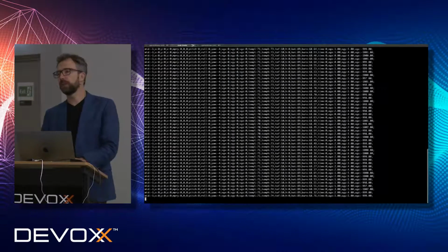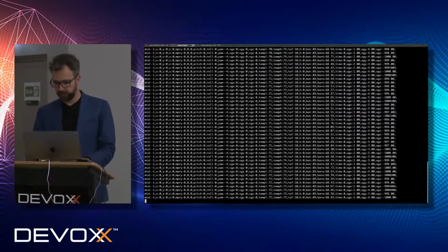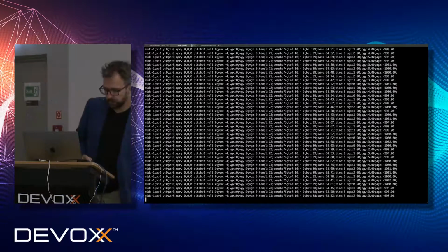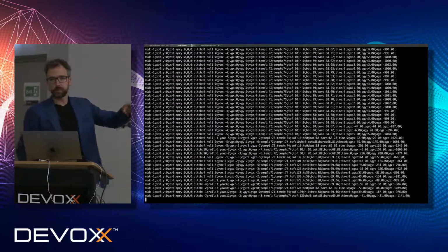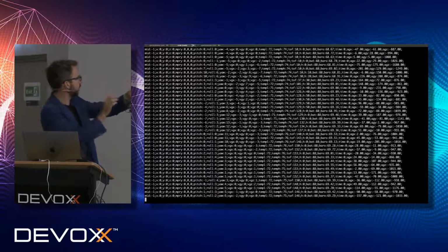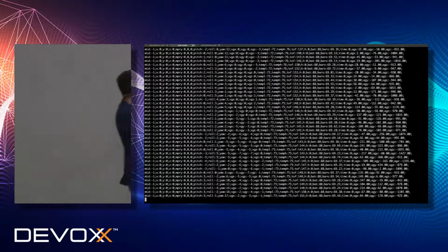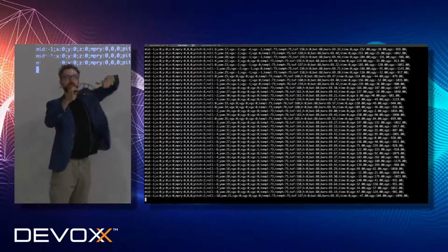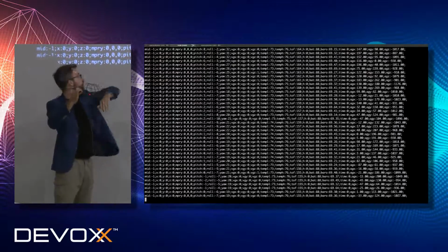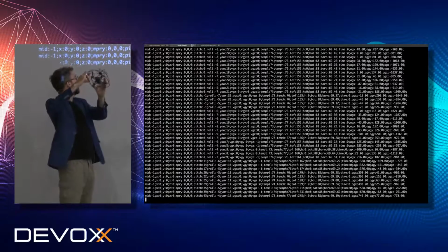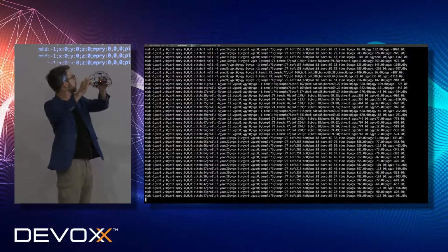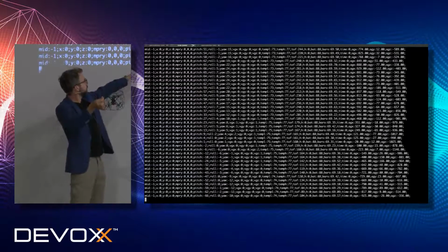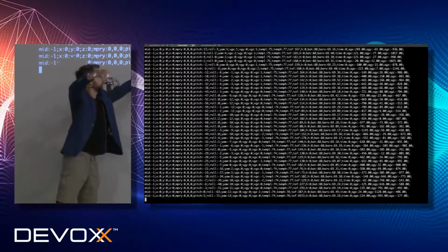This is the telemetry that's coming in. It's just one big string. I'll zoom in a little bit more later, but you'll see that there's a lot of information here. For instance, just here, this is the pitch. The pitch of a plane or of an aircraft is this movement, and if I pitch the drone, you see this number changing. And if you roll it, you see this number changing.